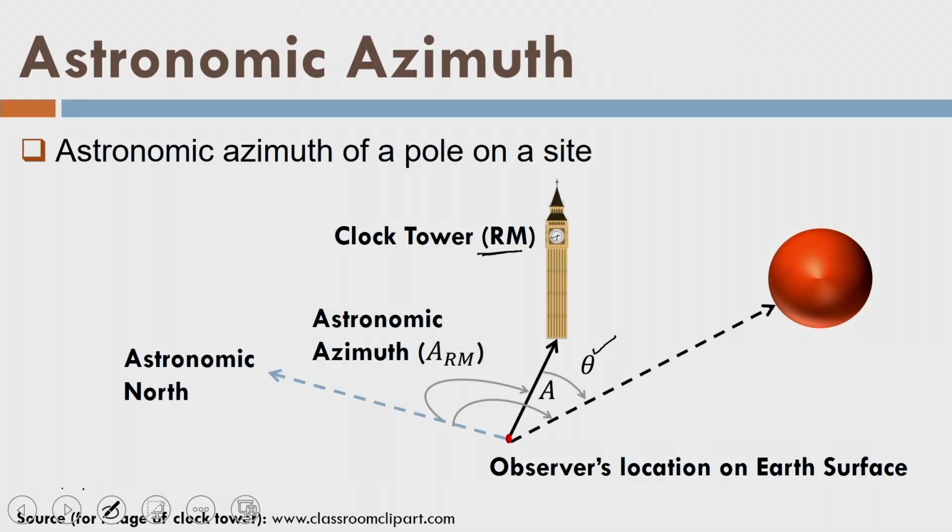There is some contradiction, because we are observing the sun on the surface of the earth. So, now we need to make some corrections so that we bring our coordinates, that is, we are measuring the altitude of the sun. So, I will bring the altitude of the sun with respect to the center of earth and not with respect to the surface of earth. Let us look at what corrections are needed here.